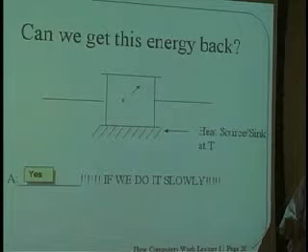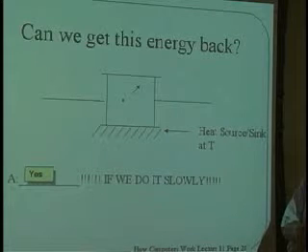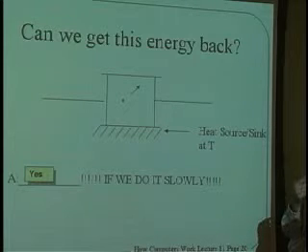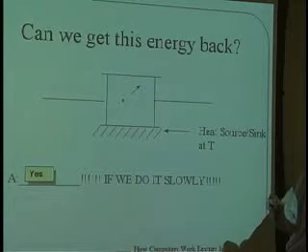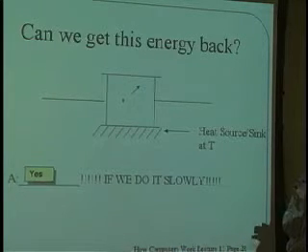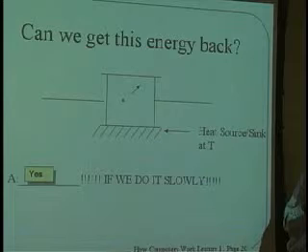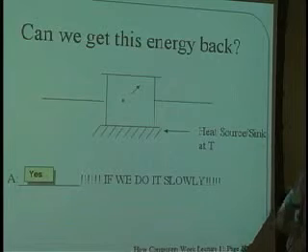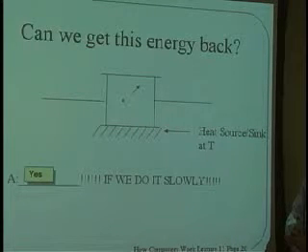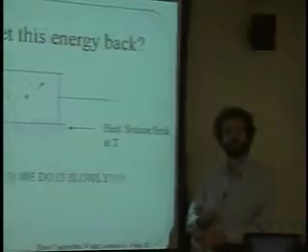If I fill up the bathtub, and instead of using a half-inch pipe, I use a turbine, and I fill up the bathtub very, very slowly so that the amount of energy dissipated by the piping that I still must have is very low, then theoretically the turbine can give me all of the energy that formerly would have been lost in the piping. However, if I try to do it too quickly, the remaining piping will still dissipate some of the power.